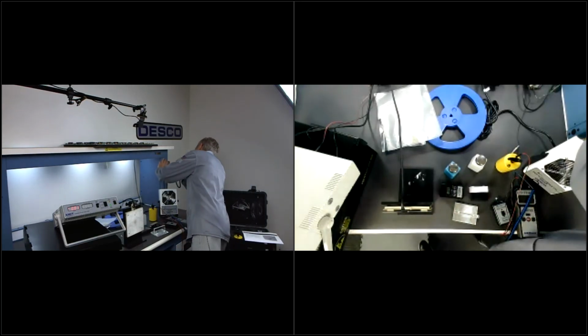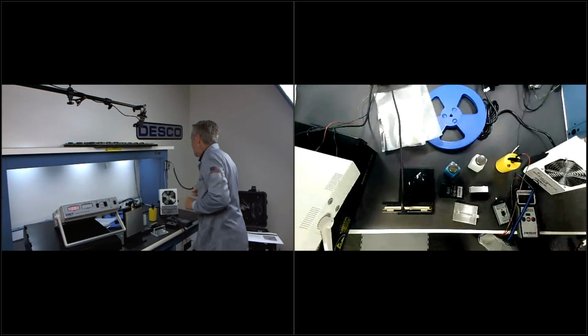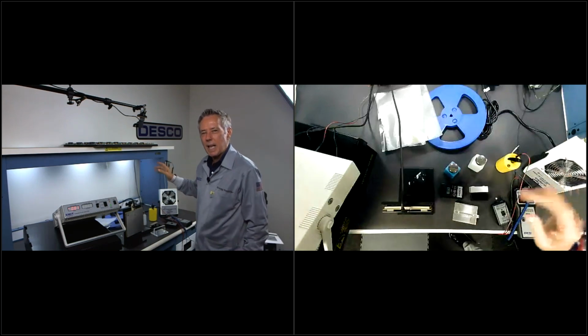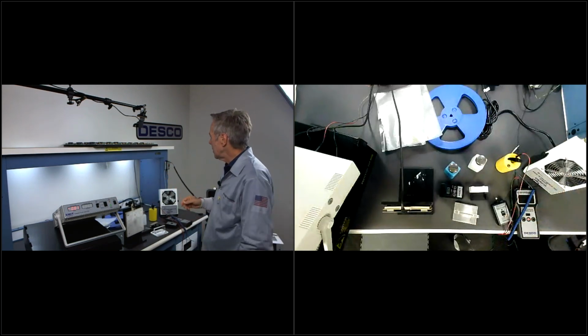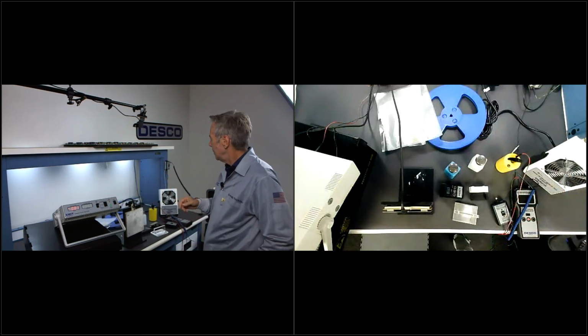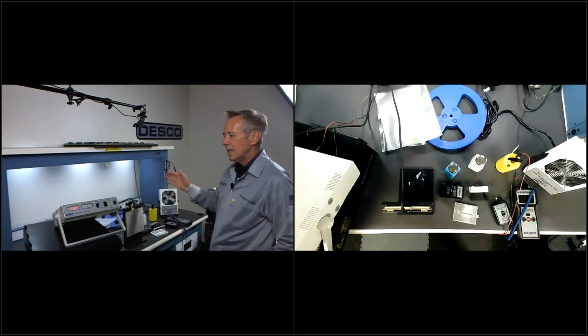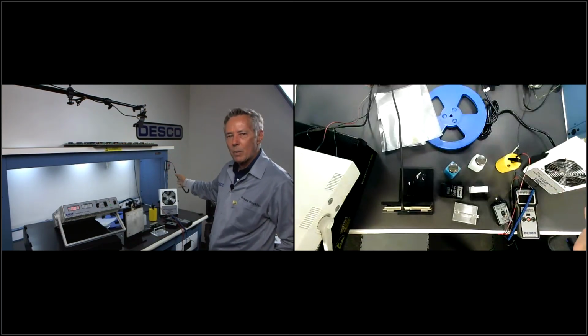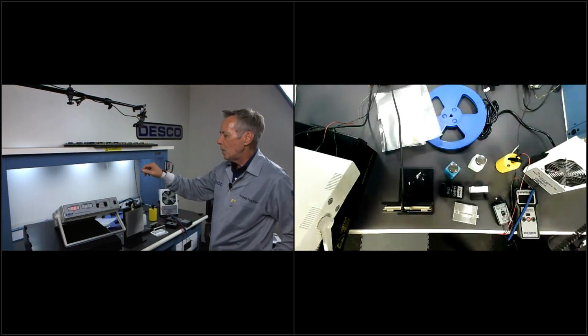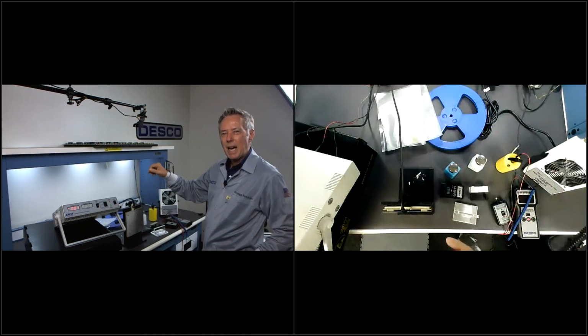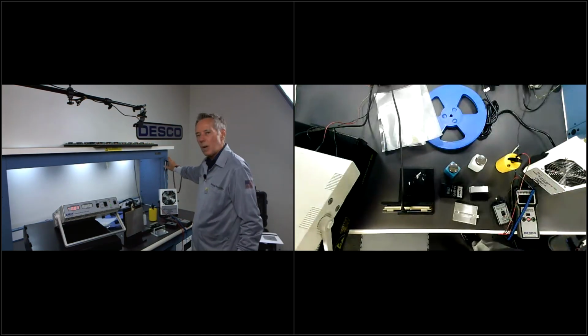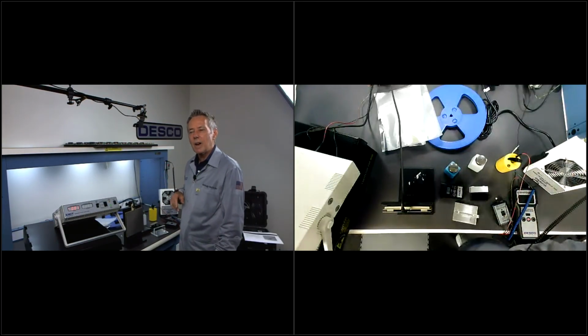I'll plug back in. And this monitor has about an 8-second delay in order for some circuitry to work. So we'll give it a couple more seconds. And you're going to see that I'm alarming now. With my resistor cord, or with my cord with a resistor in it, I was safe. With this with no resistor, I'm not safe. So there's other ways we can identify that, but that is one of the nice features. Now notice it stopped alarming.